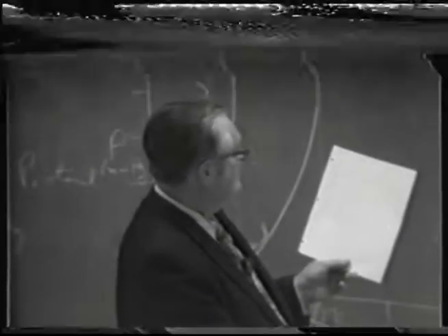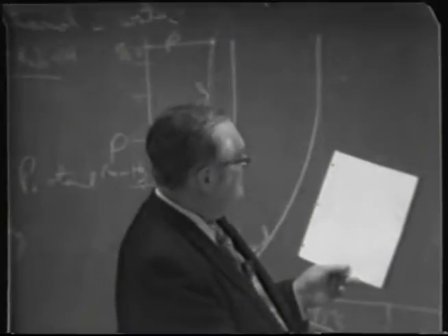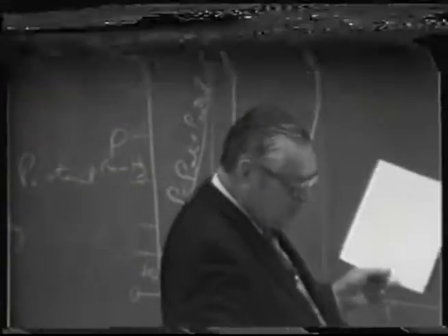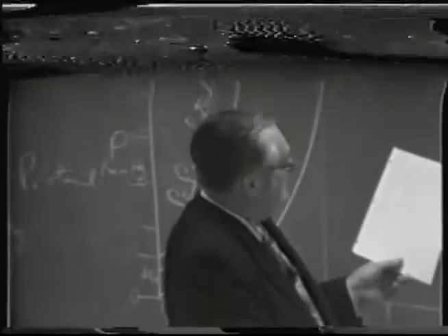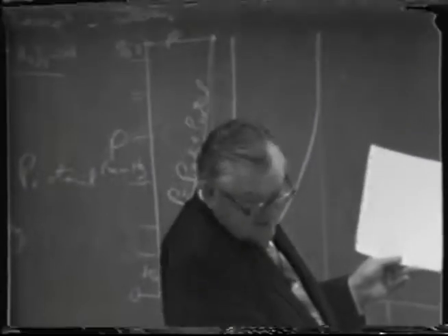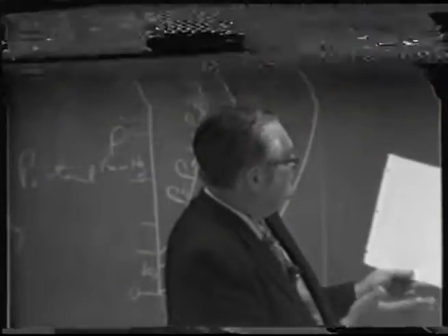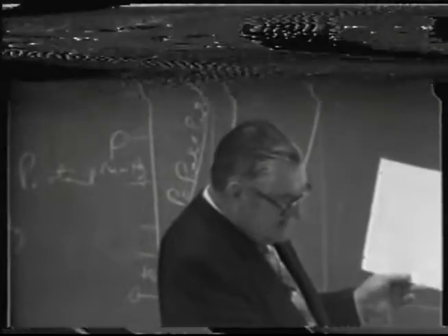Isopropanol forms one that is also a homogeneous azeotrope, but the percentage of alcohol is somewhat less: 88% on a weight basis, but only 68 on a mole basis. Then normal propanol is similar, except its alcohol concentration is a little bit less than the isopropyl.